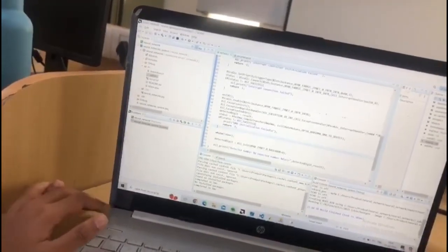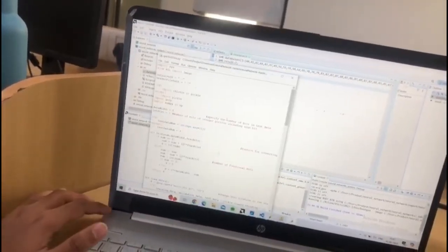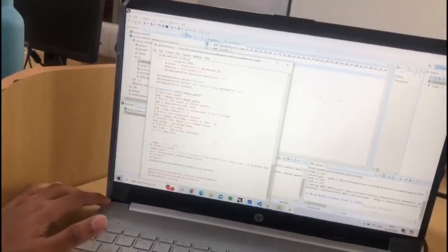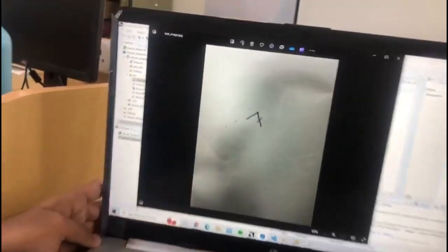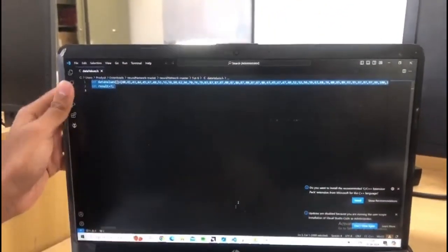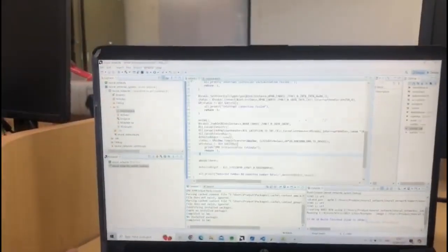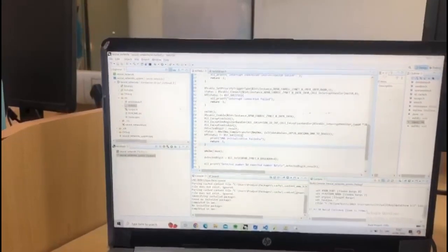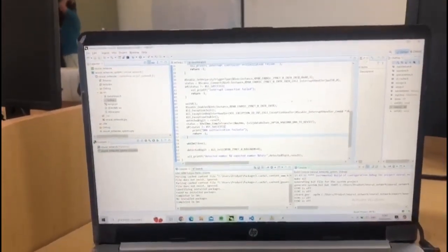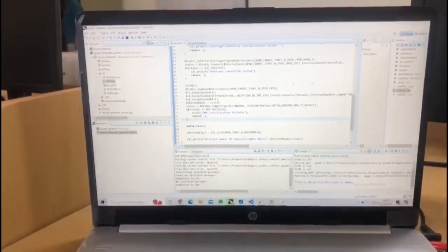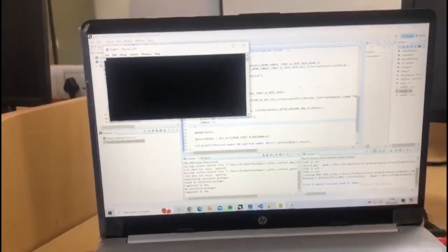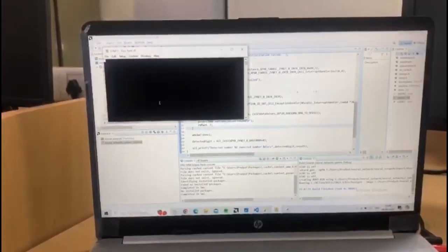This datavalues.h is generated using a custom Python script that takes the image path as an input and outputs the header file. This is the image that we are using, the digit 7 is written here, and the Python code outputs this header file, which we can copy and paste into the Vitis code. After doing that, we build the project. We use a standard serial monitor like Teraterm, with the baud rate set at 115200, to capture the output from the processing system of the FPGA.